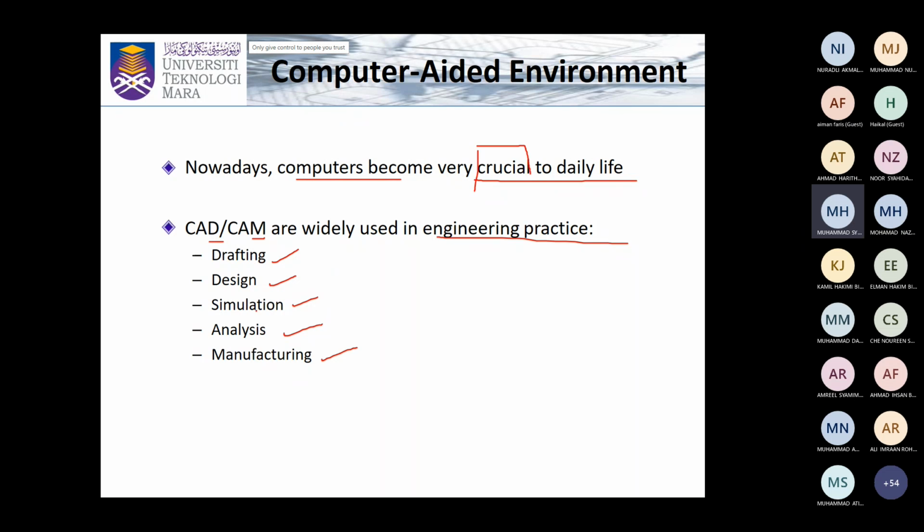The difference between simulation and analysis: in analysis, we want to diagnose errors in the model or product which you're designing. Simulation is such that we want to identify how the product moves or behaves in a kinematic situation, if you have a product with mobile joints where there is a motion of mechanism in place. At that time, we can simulate the movement. So analysis is to troubleshoot the situation. In simulation, you troubleshoot as well, but it's more of the kinematic movement of the product.